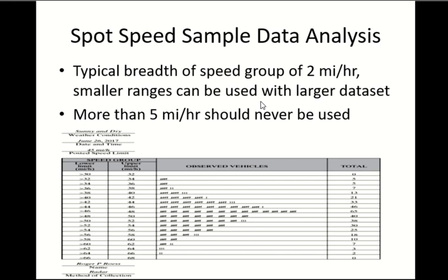So instead of that, what do we do? We just put lines, vertical lines or inclined lines. If you counted 4 vehicles, there will be 4 lines. If there's a 5th vehicle, I'll not put a 5th line, I'll put an inclined line. So every 5th vehicle is an inclined line.